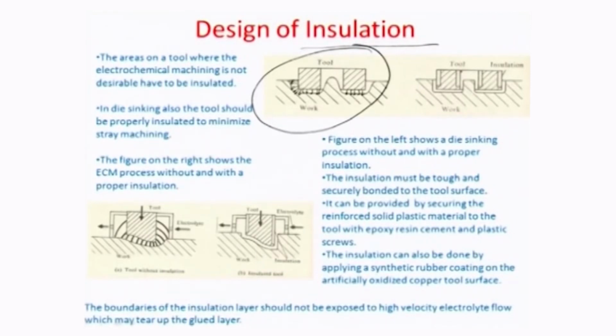And therefore, as you can see here, if we were intending for some size of the hole that we were trying to drill with ECM, maybe the hole has gotten extended and there is a lateral cut, thus ensuring that the hole is broader in size.